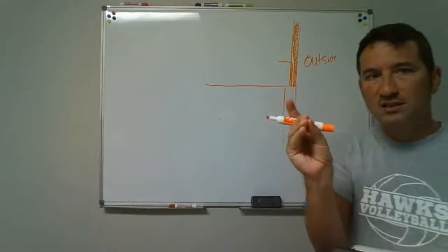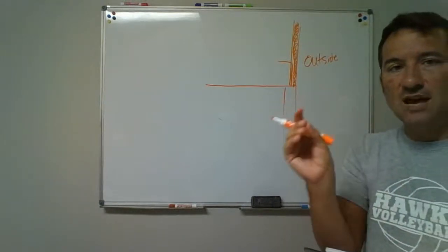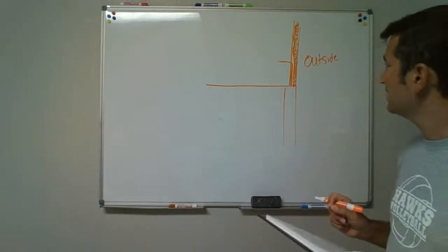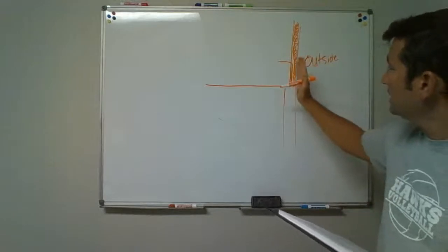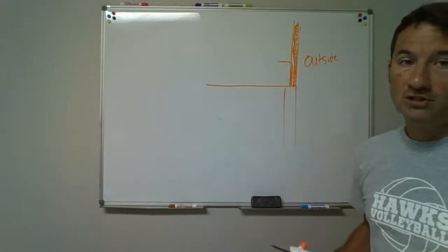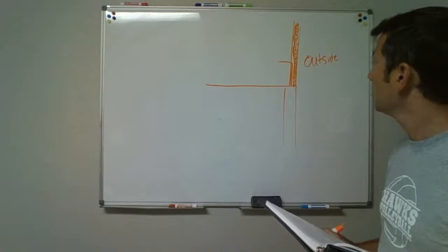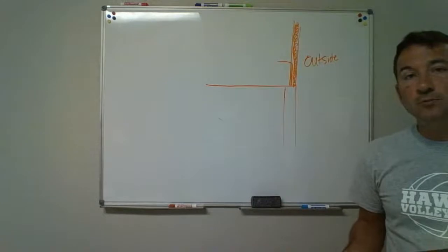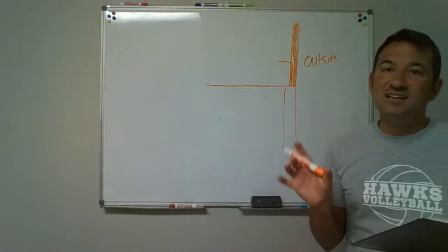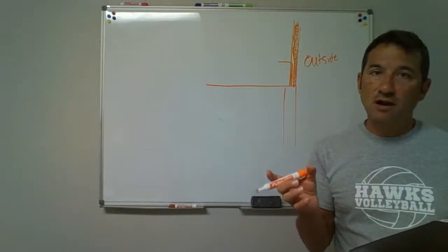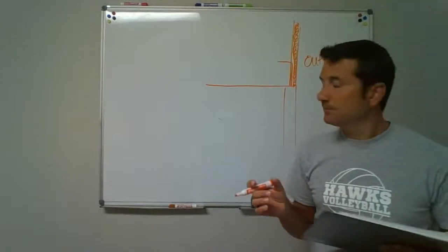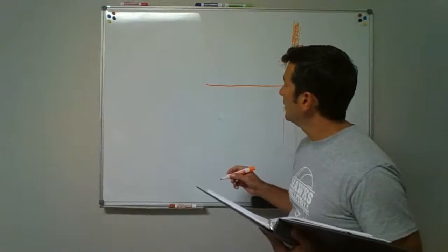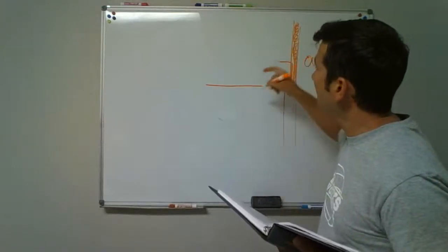If you compress the insulation, it loses that R value, that insulation value that it has for protecting it. So we need to keep that water line as far forward as possible when we run it in an exterior wall. You'll notice that on the homes we do, we'll actually wrap insulation around that line. We'll do that when they might have blocking back in the wall. Okay, so maybe they're putting some blocking in the wall for cabinets.